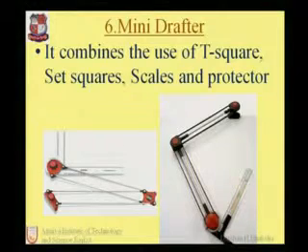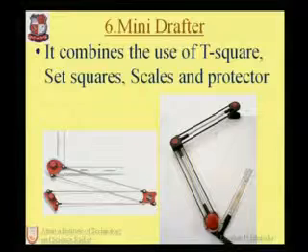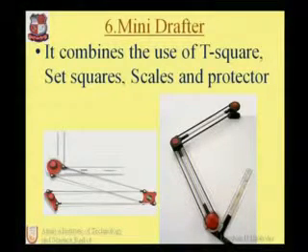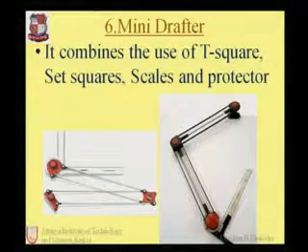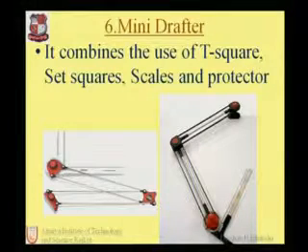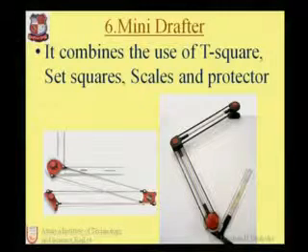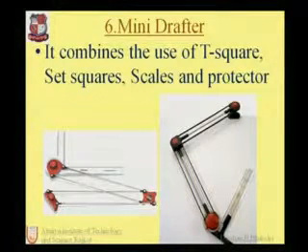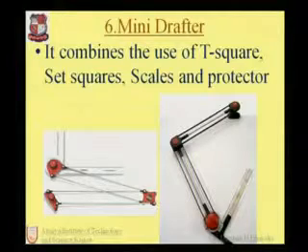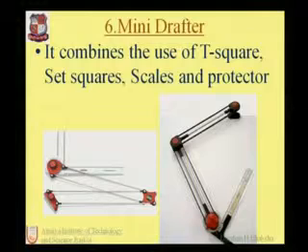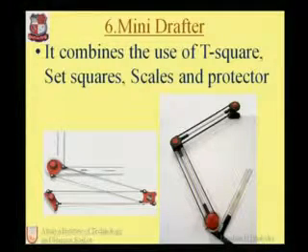In this case, if you want to draw by using the mini drafter, clamping it with the drawing board to the sheet is a must, because only with the clamping device can the mini drafter be used on the sheet using the drawing board. First of all, we will clamp the mini drafter on the drawing board using the sheet, and then we can rotate it, move it, and slide it to any place on the drawing sheet as per our application.